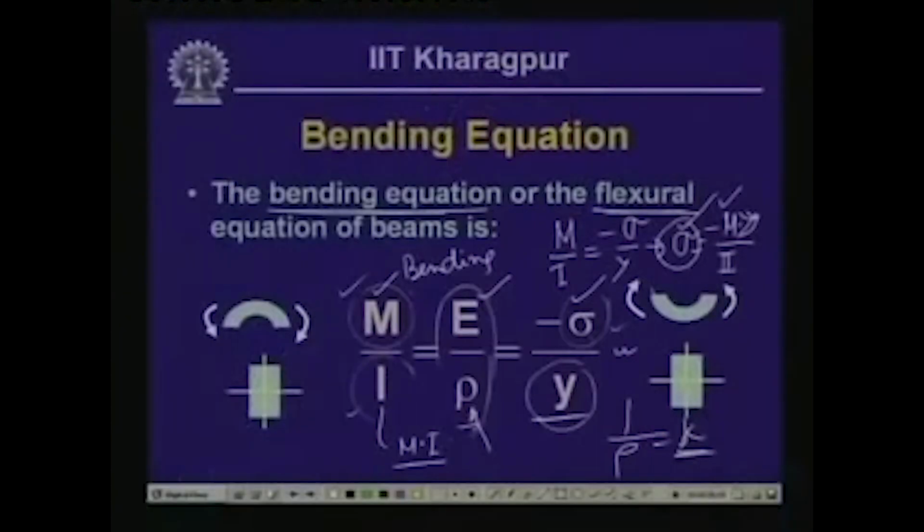Of course, the terms have different meanings, and please note here the sectional parameters: in case of a twisting moment acting on a shaft, we used the polar moment of inertia J, which corresponds to the sectional property. In this case, when we are dealing with bending, we are again dealing with sectional properties, but we are computing the moment of inertia about the axis lying in the plane of the cross section.